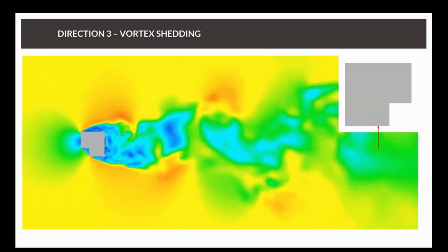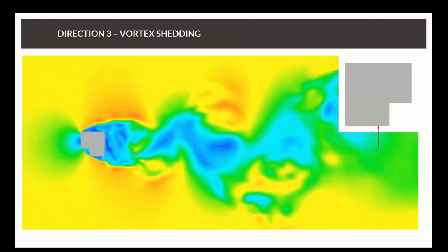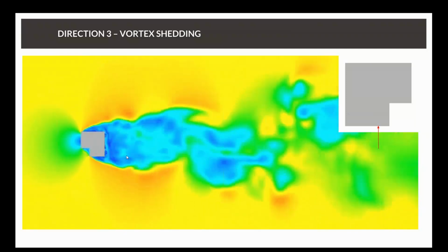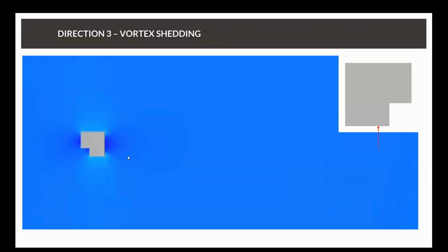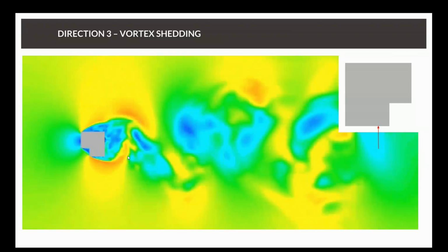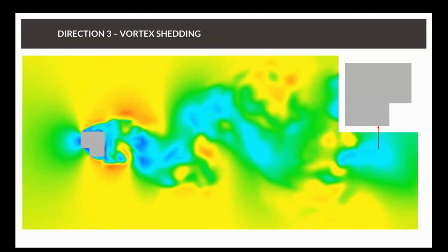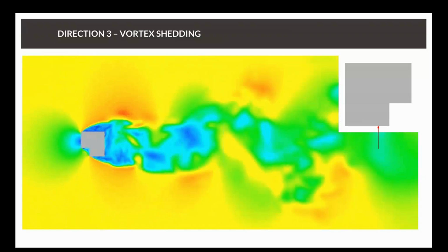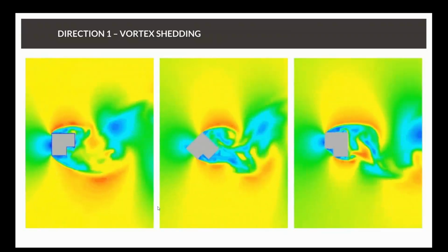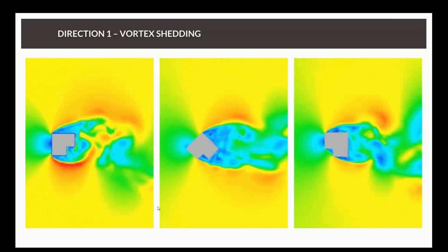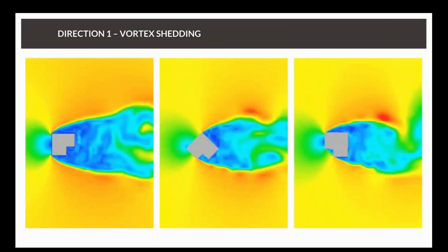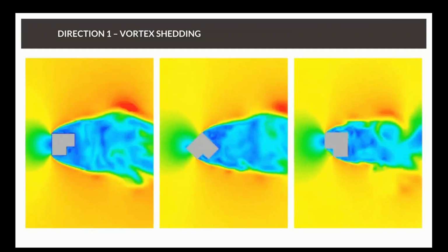So there are some huge variations with this particular angle too. You can even see flow quite close to the building, just returning. It's all coming back on itself. And this is at a cut plane roughly half the height of the building, so at about 40 meters. You can see them all side by side too, which is a nice thing to do, because it helps us understand if we have a problem in one direction or all directions, once we start to compare these results.